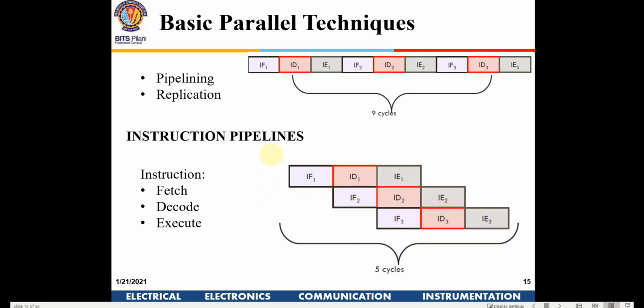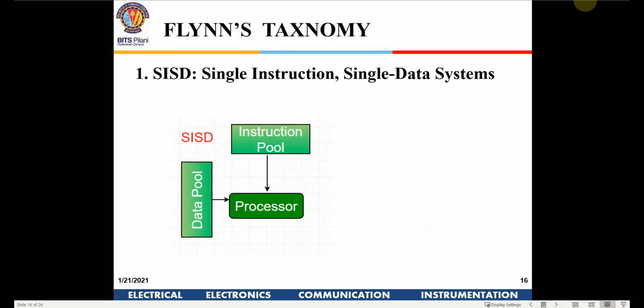So the 8086 essentially is a pipelining architecture. What is pipelining? Is it understood? There are some temporary registers where, while the first instruction is being decoded, the next instruction will be brought and placed into a temporary register. While this is being executed, the next instruction will be decoded, and the third will be fetched. So is the pipelining process clear to all of you?